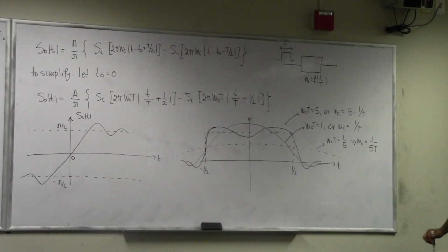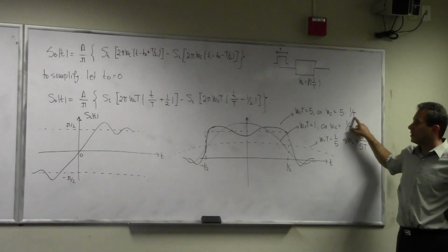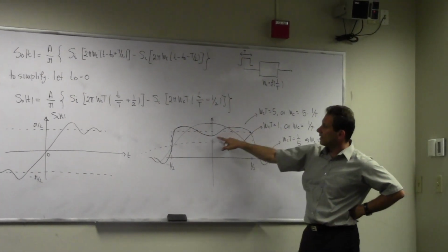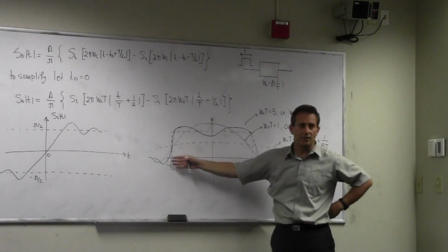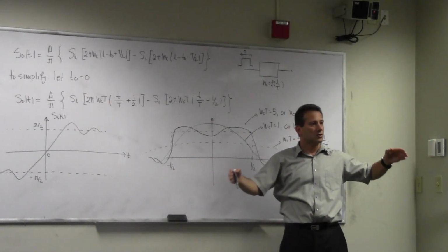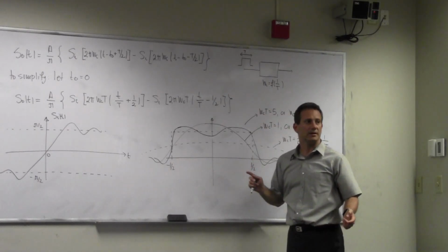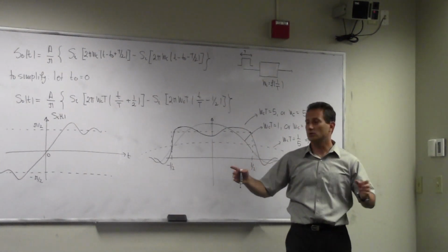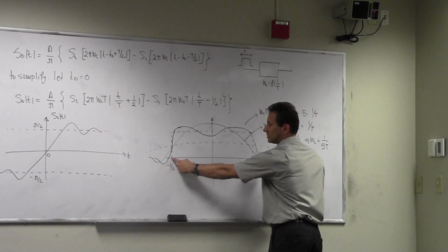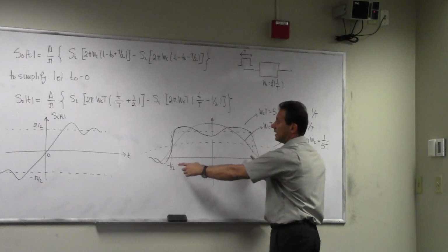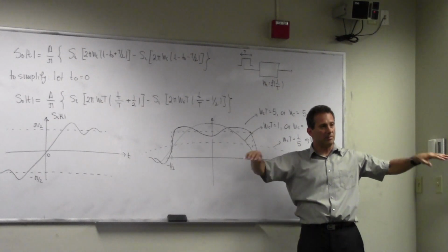Right? 1 over T. If my bandwidth is relatively large, 5 times 1 over T, what comes out is a very localized pulse, right? It has some ripple here, but it actually falls right off and it kind of dies quickly. So my pulse still occupies pretty much what it used to occupy. There is no dispersion in the time domain. It used to start with this here is T over capital T. So it used to start as being of a duration T, and it kind of ends up being the same duration. There's some ripple to the other side, but that ripple dies very fast.